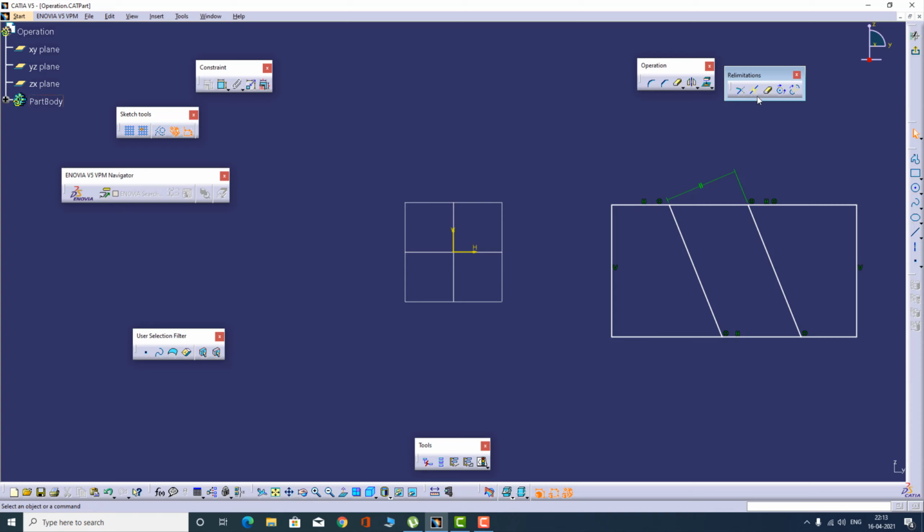If I select the line from the middle, you'll see it gets broken into three, because it will get broken with respect to this line, and here it will get broken with respect to this line. Let me just select it here. You'll see now this is in three pieces. So that is how break and keep works. Now let me just delete this.